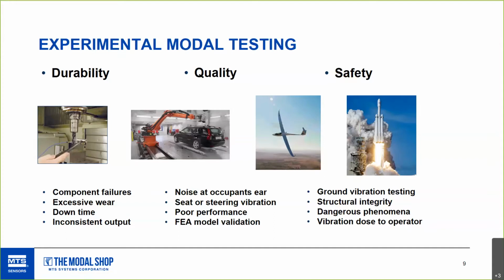Obviously this is where we can't have stuff fail under operation, or even if there is excessive vibration on a machine that a person's operating, and at that speed it shakes a lot and can increase the vibration dose to the operator to the point where you have a human vibration problem because of a resonant frequency of that machine. So it cuts across all breadths as to why this sort of testing is important.